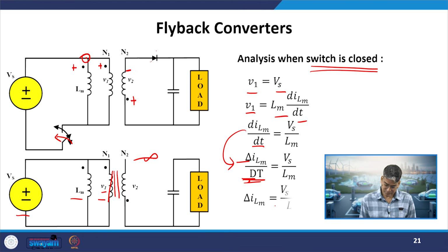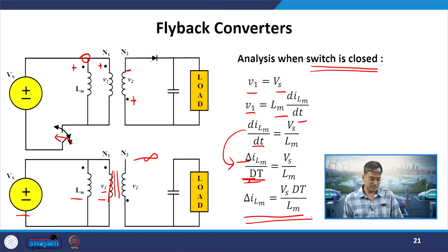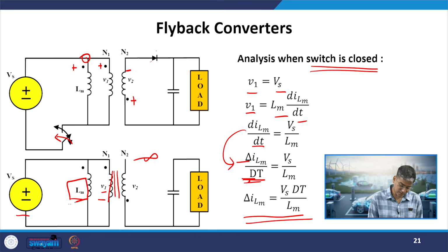So, if I realize that, I will see the energy stored in the magnetizing inductor. So, what is Lm? It is the magnetizing inductor of the transformer. If I see the practical transformer, it has various types of losses: winding resistance loss, there will be leakage flux, and there will be your magnetizing inductor and core resistance. These are the components which will be present in the equivalent circuit of a transformer. Here, for the simplicity of our analysis, we are not considering the other components.